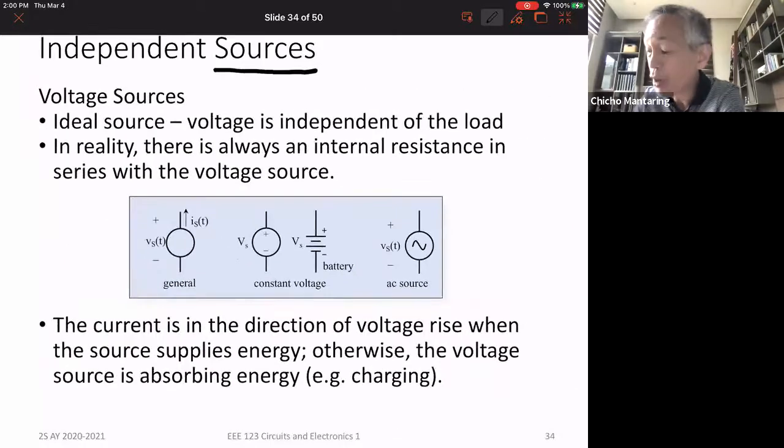Okay, and then later on, we're going to be studying AC circuits. This is a symbol for your AC source. Now, you might ask, bakit may polarity yung AC source? Bakit may polarity? Well, you always have to have a reference polarity. You know, when we do AC circuit analysis, you have to have a reference polarity because all of the voltages and currents in your circuit would have to be specified with respect to this reference at a given point in time. No? So kahit na AC yung source natin, ibig sabihin nag-alternate yung polarity, at a particular instant in time, no, you have to show the polarity with respect to all other voltages and currents in the circuit.